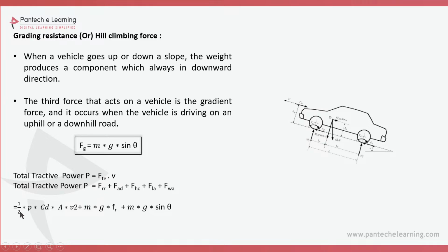Okay, we can see half into rho into CD into A into V square is the drag force. M into G into FR is the rolling resistance. M into G into sin theta is the gradient resistance. Okay, so now we have seen the acceleration force.